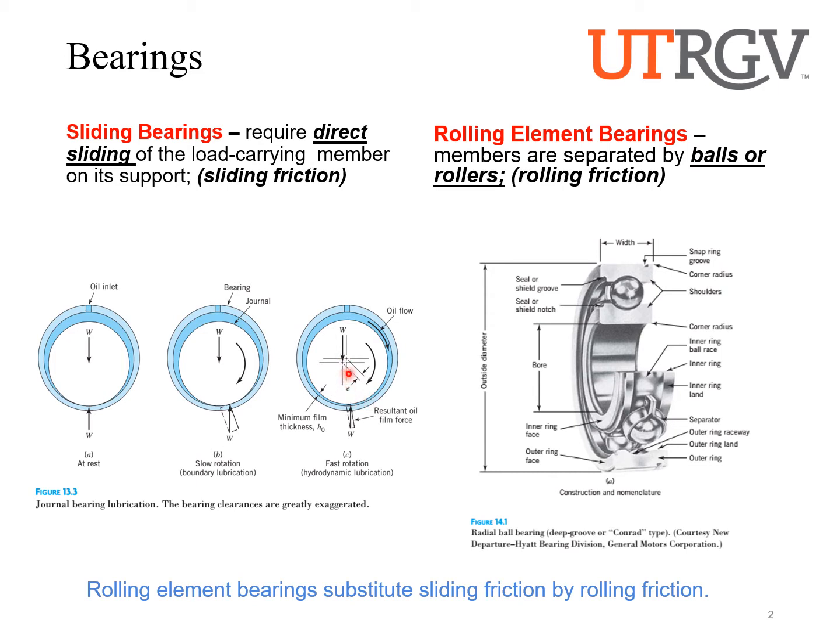But it takes a couple of turns for this to get going and to have this lubrication that's going to protect the bearing. The sliding bearings are called sliding bearings because you have members sliding past each other, right? And yes, you have some sliding friction, which is a little bit high initially, but after a couple of rotations, you have the film and that sliding friction is going to reduce. Again, when they're no longer touching and you've got the film, the wear rates are very small.